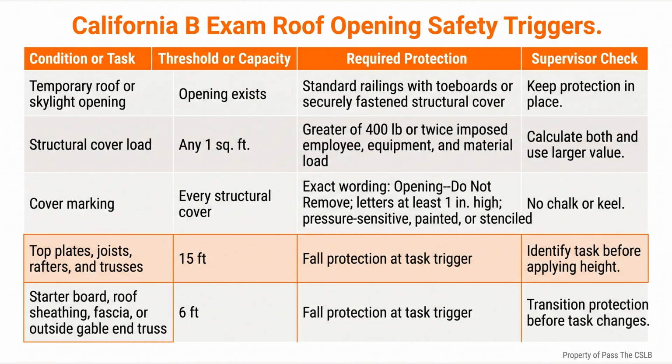Inspection-ready work starts before framing. I confirm the approved opening size, member sizes, spans, bearing, hardware, and engineered notes. I verify that the product and rough opening agree, then coordinate the curb, flashing, cricket, clearances, and safety protection with the trade sequence. I measure the controlling dimensions instead of estimating.